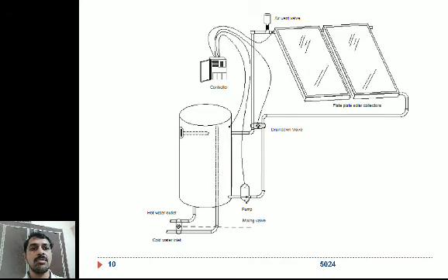The storage tank could be a heat exchanger where the closed loop antifreeze fluid, always antifreeze fluid, will be utilized to circulate in the collector system that will be exchanging heat to the actual fluid, that is water, in the heat exchanger in this storage tank. Clear?